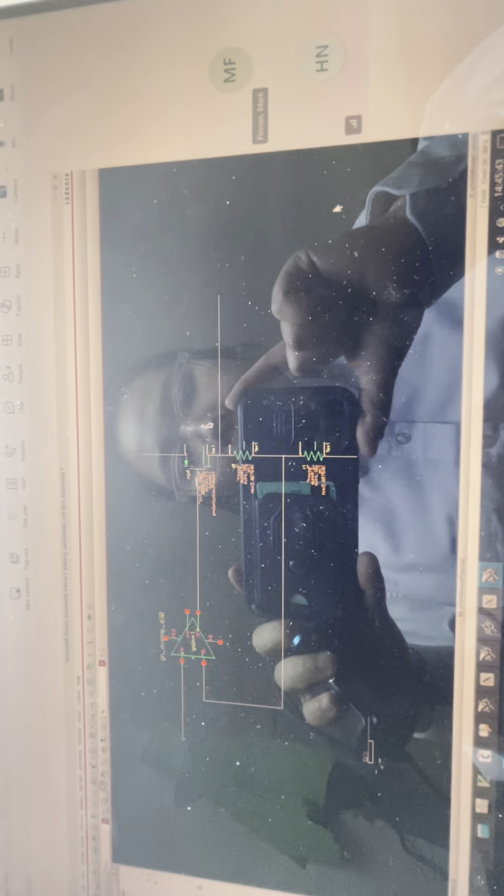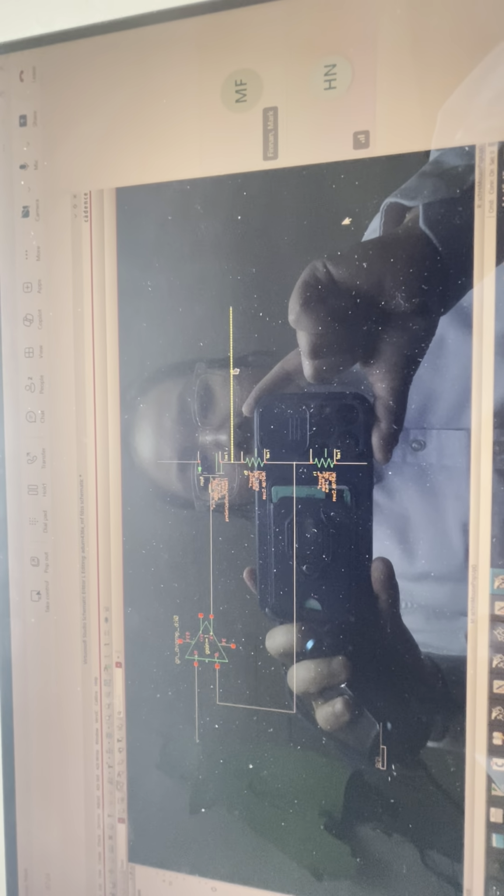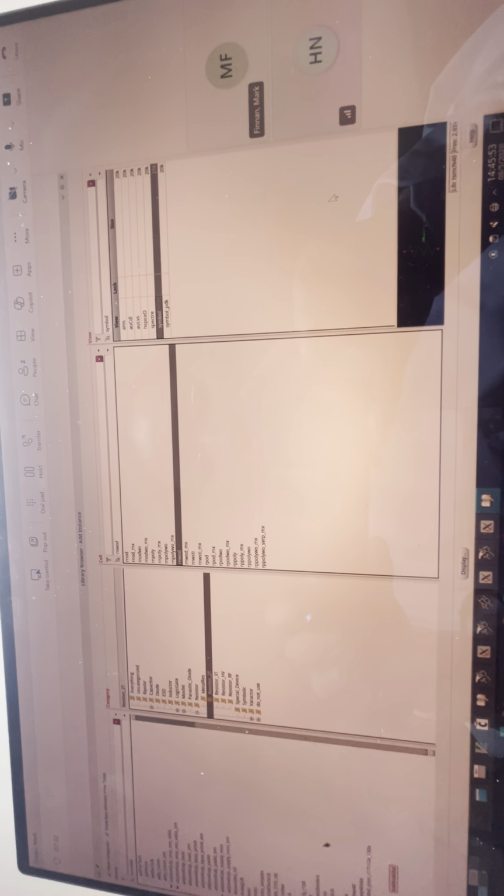So the way the LDO works is that it just steps the voltage down. It varies the resistance of this device such that if there's a current load here, the voltage here stays constant. And that's what the loop is doing. So the next thing to do in your case is actually to add a current load to it. So to do that, you can